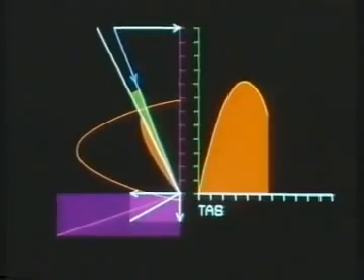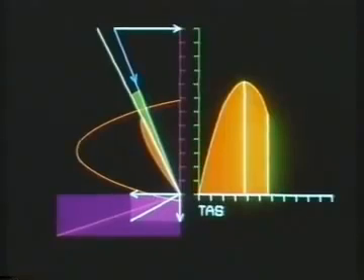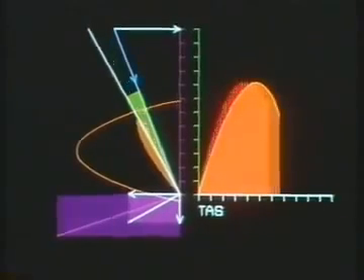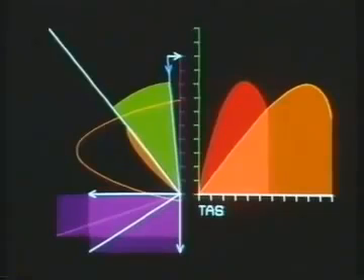The principal limitation of fixed-pitch propellers is that there is only one speed at which they work at peak efficiency. This propeller is a fine pitch propeller, giving good performance for takeoff and climbing, but a relatively low maximum speed. By increasing or coarsening the pitch, the maximum speed can be increased, but there are practical limits to the size of the blade angle that can be used, since too large an angle might mean the propeller could be stalled when the aircraft is stationary or moving at low speeds.